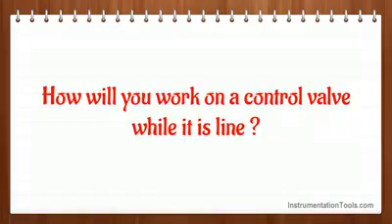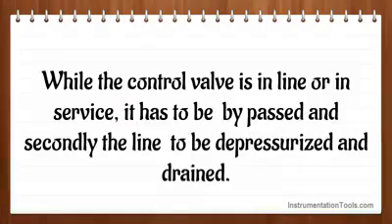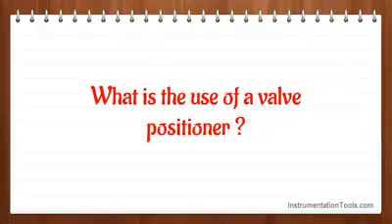How will you work on a control valve while it is in line? While the control valve is in line or in service, it has to be bypassed and secondly the line has to be depressurized and drained. What is the use of a valve positioner?